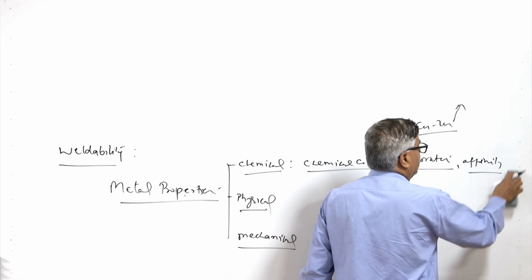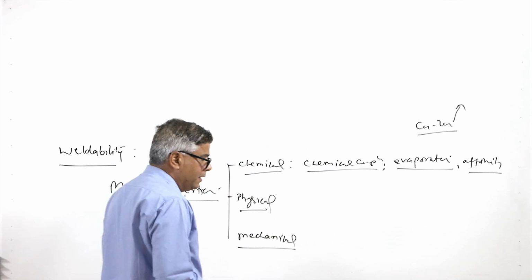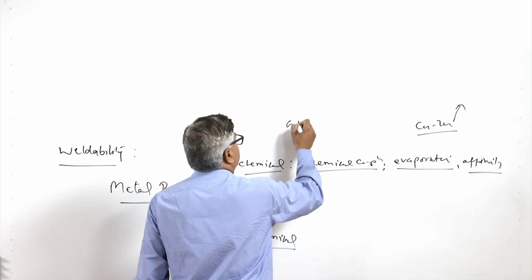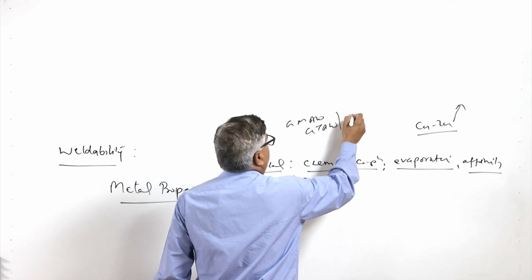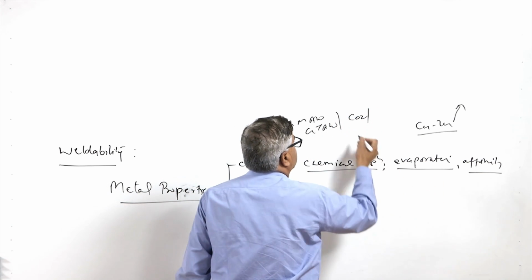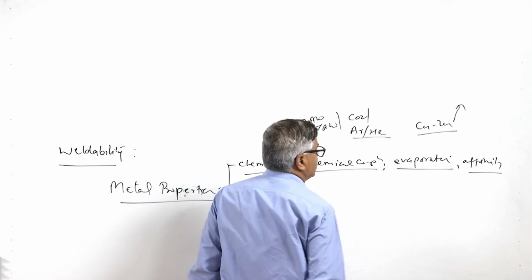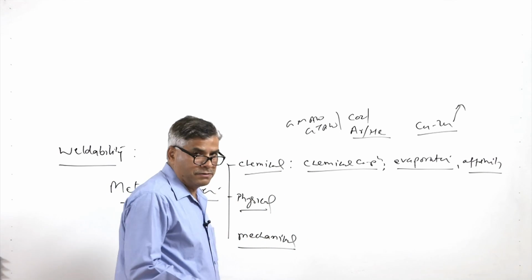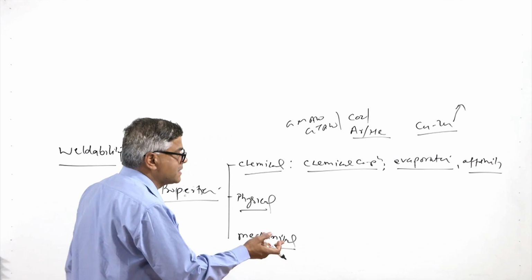That is why they need a special protective environment like inert gases in processes like gas metal arc welding or gas tungsten arc welding, with either CO2 for stainless steel, or argon and helium for aluminum and magnesium alloys. Titanium alloys are also welded this way, because titanium has very high affinity to oxygen and nitrogen, and when it reacts it embrittles the metal.